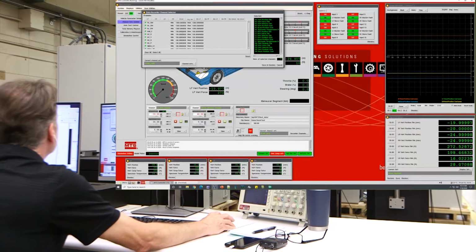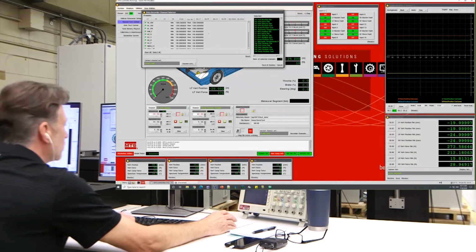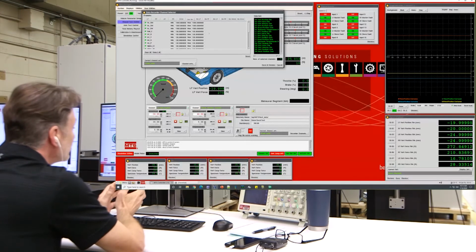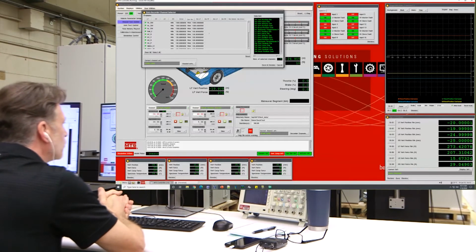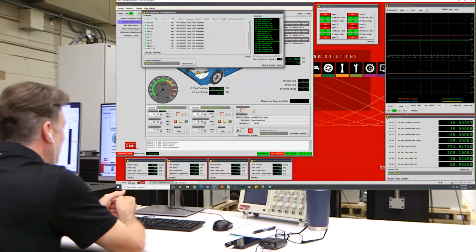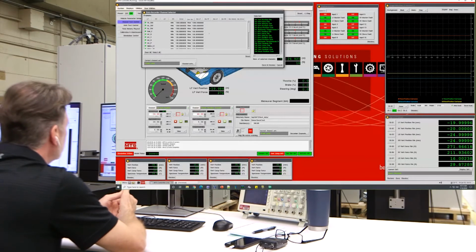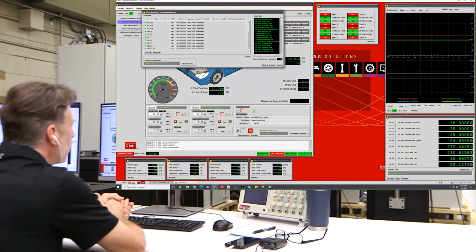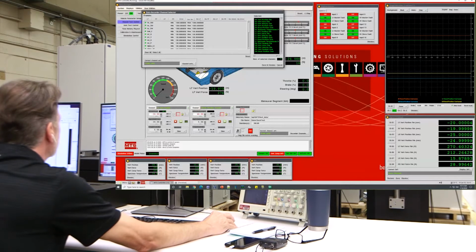We have a driver. We have a number of user channels, and these are not physically present within the controller, such as an analog. These are mapped in that shared memory, that interface between the vehicle simulation and the physical system. So a customer may want to collect a number of additional signals that are in the model, or maybe associated with a block that they've added to the model. So they can go into the Simulink environment and map these channels. In this case, this customer is primarily interested in ride, and so we've got a number of accelerations here that are coming over in addition to the traditional channels we collect.